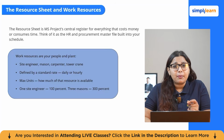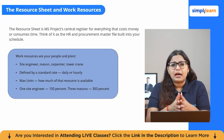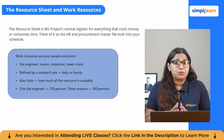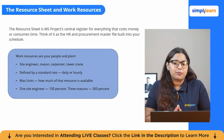They are defined by the standard rate, which is typically daily or hourly, and by max units, which tells MS Project how much of the resource is available. If you have a site engineer, max units is 100%. If you have 3 masons available for work simultaneously, max units will be 300%. This number is critical because it is what MS Project uses to decide when a resource is over-allocated. That is when you have scheduled more work for a resource than is physically possible for them to do.